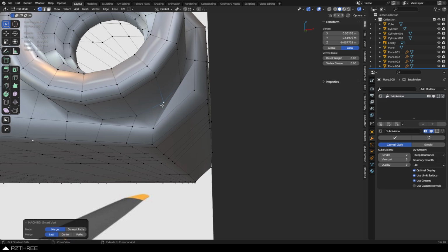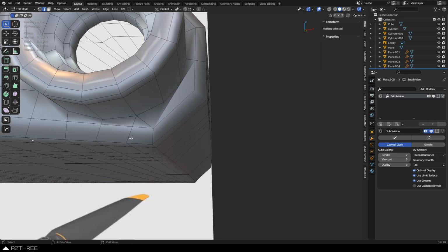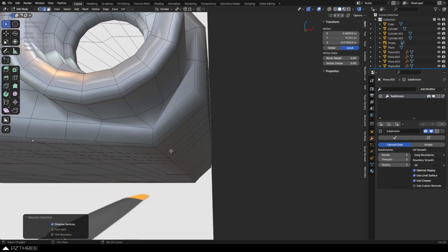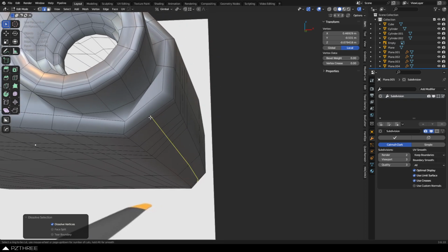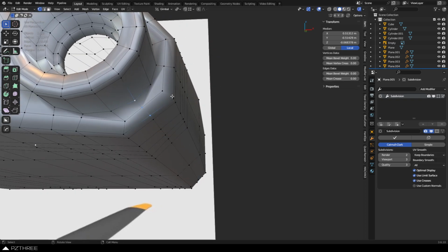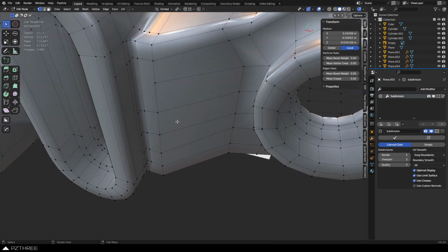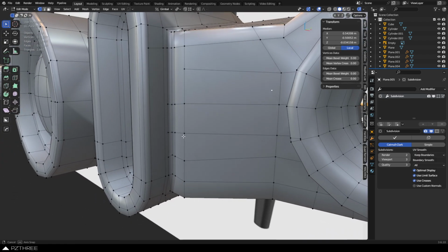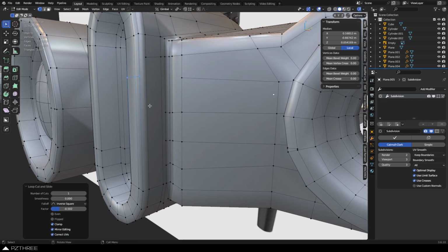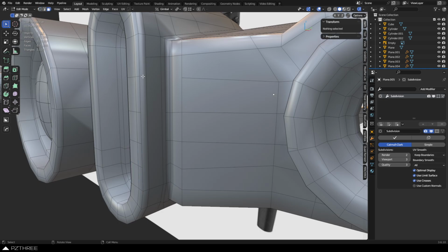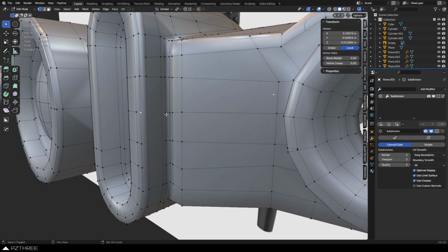This one, maybe not. We can go to there or we can go to there. If we go to there, I'm dissolving that one through. Right. Now that gives us a quad like that, so that makes a little bit more sense. Now we can loop cut here, join there. These can all be joined together. And we're creating a nice little patch like this, which is great. And you would think that we go through this whole bit of trouble here. Loop cut to that middle. See, we're going to do that back here as well. Add a loop cut as needed. We can just join these now.